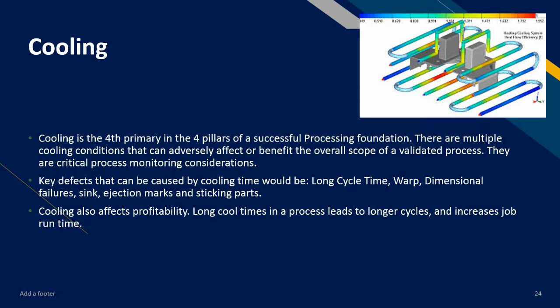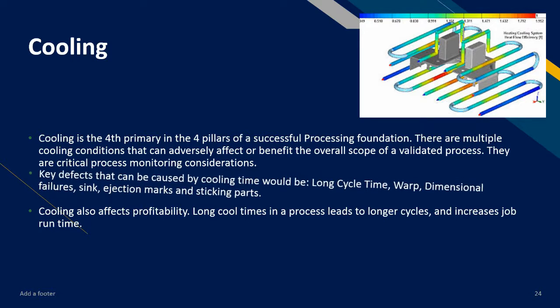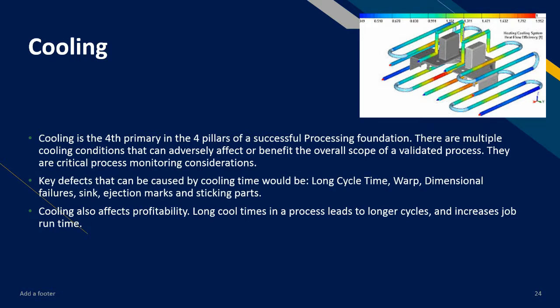Key defects that can be caused by cooling time would be long cycle times, warp, dimensional failures, sink, ejection marks, and sticking parts. Cooling also affects profitability. Long cooling times in a process lead to longer cycles and increased job runtime, which affects the overall productivity of a company.